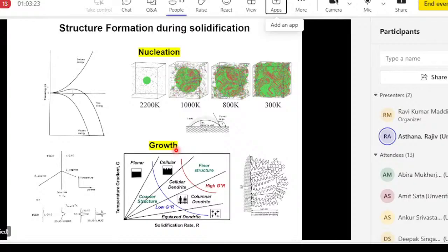And here is the basic idea. This is the solid metal, this is the liquid. As solidification takes place, this interface moves from left to right, and more and more solid forms. But if you look at the temperature gradients, this is how the temperature gradient looks in the solid and in the liquid. The liquid is supercooled in front of the interface. So if you initially have a planar front, it moves into the supercooled liquid and a perturbation forms. This kind of protrusion forms and it can grow and then shoot side branches to create what is called a dendritic structure. So we have dendrites forming during cooling of the metal.